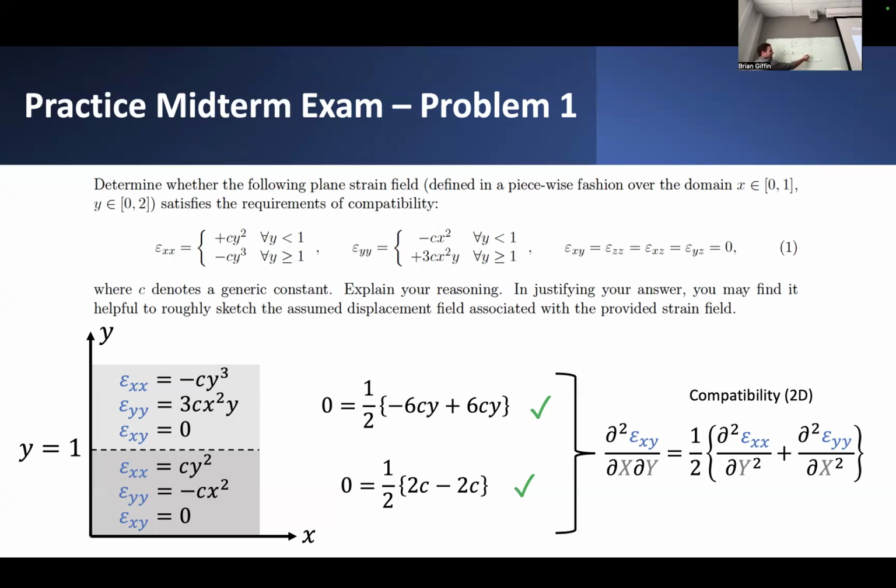So really, because this now is just some random constant, we can still compare how the resulting expression for ux varies as a function of x, and consider that kind of linear or quadratic variation with respect to x in both of these terms, and compare those terms, forgetting about the extra constant terms that might appear. And we can say, does that variation in x for each of these two terms lead to incompatibility? So for this particular problem, it means we can forget about having to deal with this extra constant of integration and really just look at the integrand term.